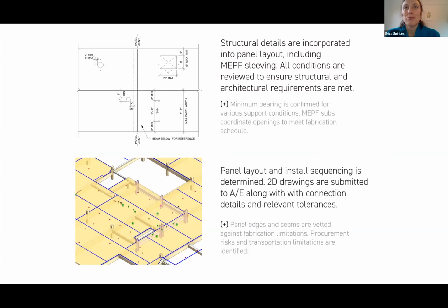So here's what that process looks like. It's kind of a 2-step process. The first step involves getting everyone in agreement on the geometry of the building, within that timber tolerance of about 16th of an inch. And so that means reconciling architectural, structural, mechanical, all trades, and figuring out exactly where the edge of deck is, for example, and then exactly the sizes of all penetrations and exactly where they'll be located in that deck.